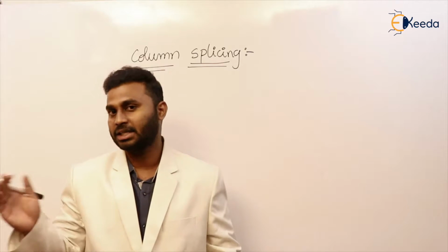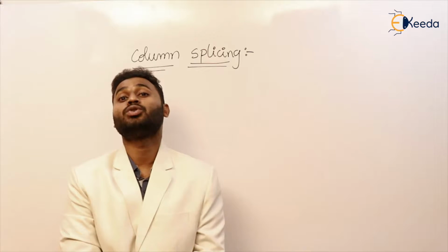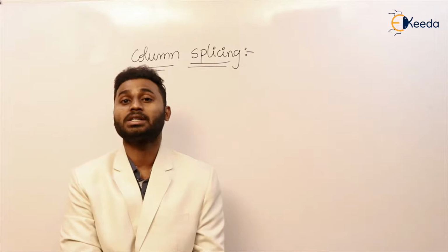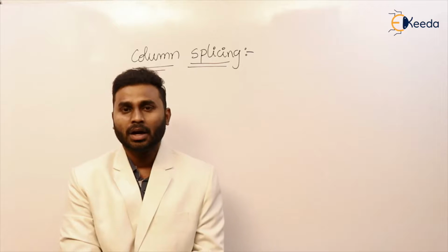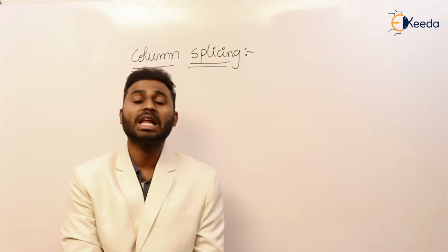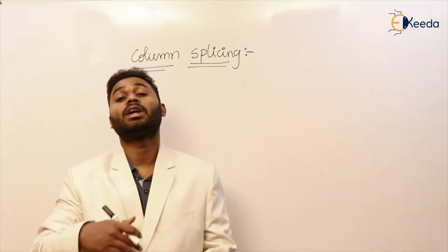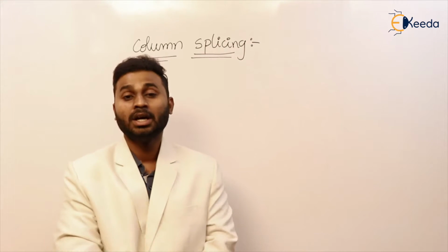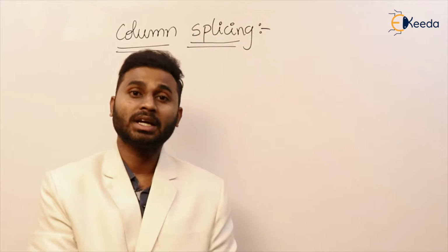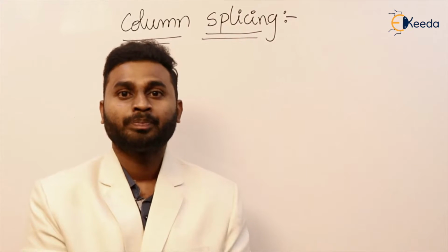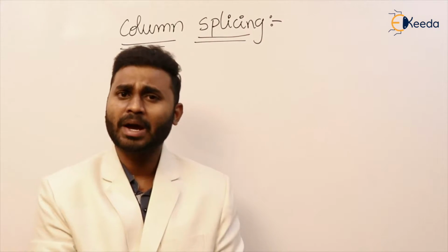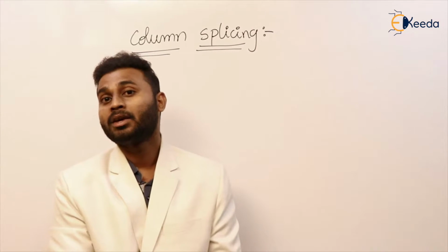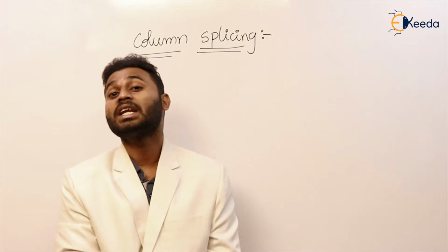Up to the example we have seen is connecting two channels. In connecting those two channels we have used connections, known as either lacing or battening. So that is also a connection. So what happened in that case, whether in the lacing system or the batten system? Think, what happened? Their cross-sectional area is increased.